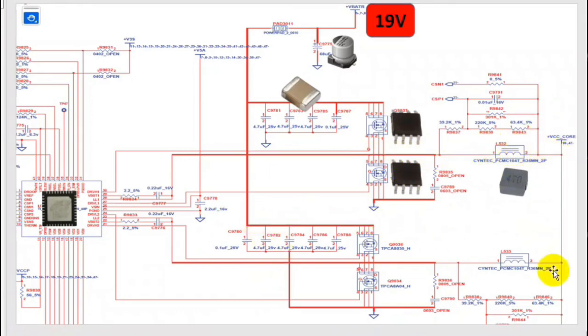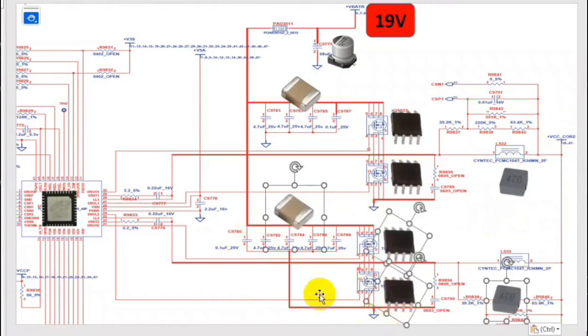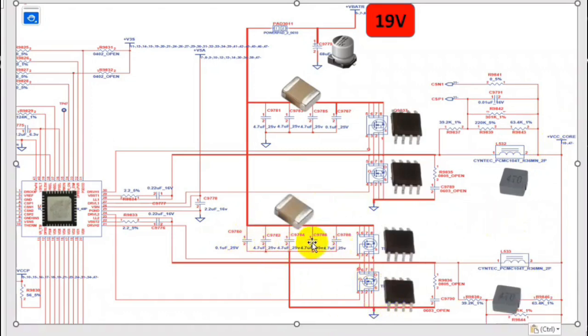The same working principle applies in this channel. This is basically the second channel, as you can see. We have ceramic capacitors here. The 19 volt will pass through this electrolytic capacitor, which is common between this channel and this channel, and then goes through this point, and here we will also get 19 volts. Do you see this bolded line here? A bolded line means a high voltage. But here, for example, we have just thin wires or paths.